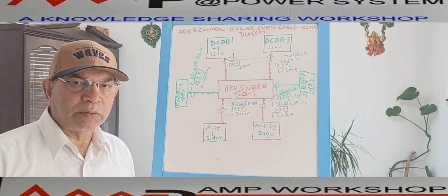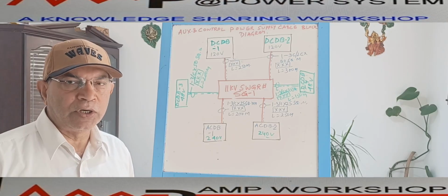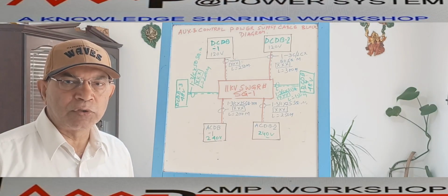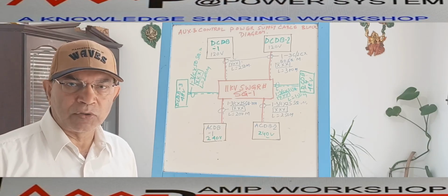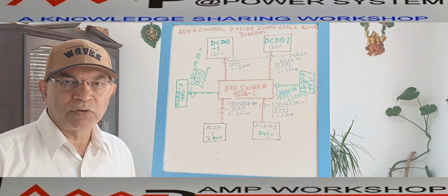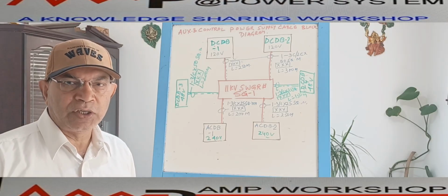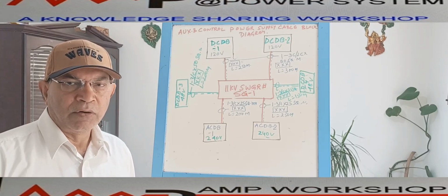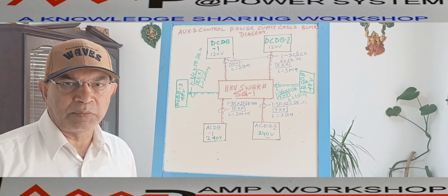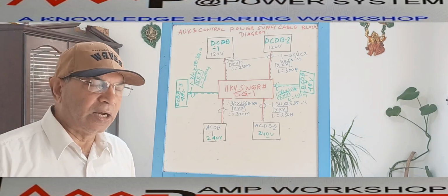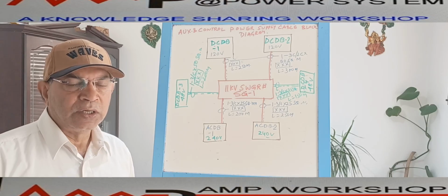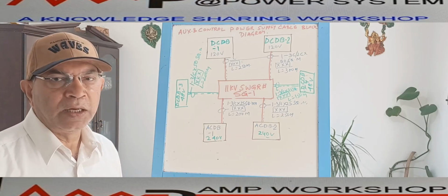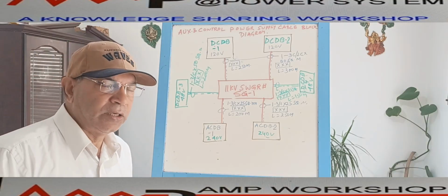And the other control supply, which is 48 volt DC or 24 volt DC, under our discussion 48 volt DC, will mainly be used for the protection relays control supply and various transducers control supply. Then we have the annunciator control supply. In addition to this, if there are any other instruments or devices which need a control supply, some auxiliary relays may need 48 volt DC supply. If there is a DC relay that needs 48 volt DC supply, that relay is also considered under this 48 volt DC. These are the two main DC supplies for the switchgear.